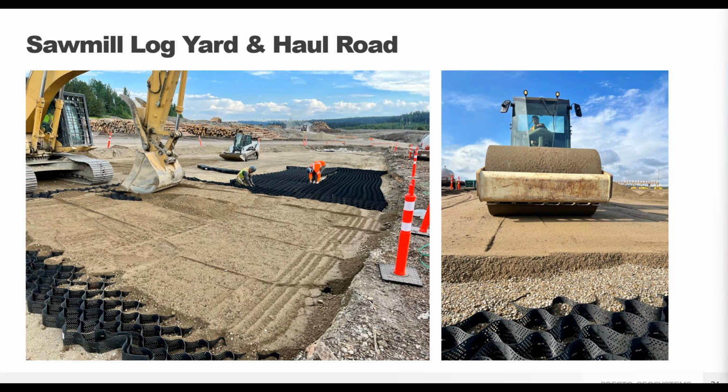Here we see a good technique tip with crews working in parallel. On the far left, the placing of the infill by the excavator, while workers expand and connect new sections of GeoWeb, as you see in the right. Far right, we see the roller compaction of the infill. Having a crew with well-defined roles allows this kind of work in parallel and install best practice, and makes for an efficient installation.